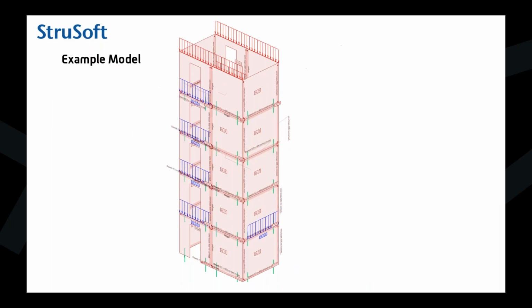We also have a really classical problem here, that we have a lot of load on the one side of the structure, but not on the other. So the vertical connections will have a lot of stress in this case. And the same happens if you're using hollow cores. Hollow cores will distribute the loads only in one way. And if you notice, a few loads are blue and a few are red.